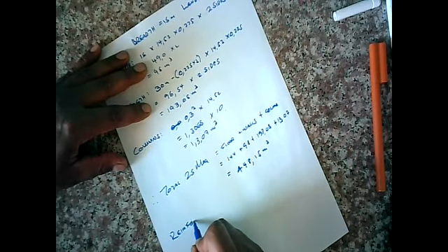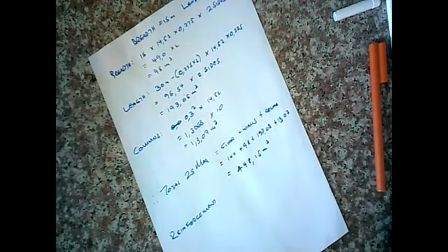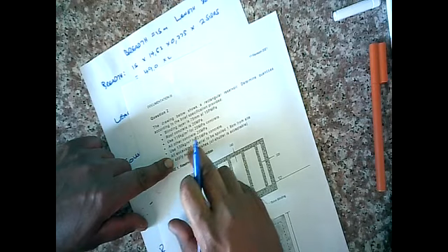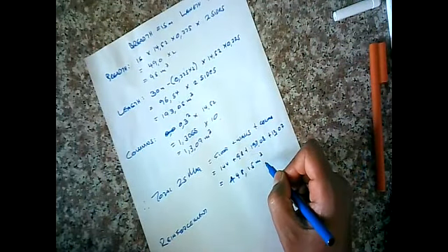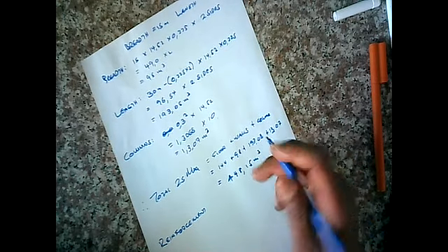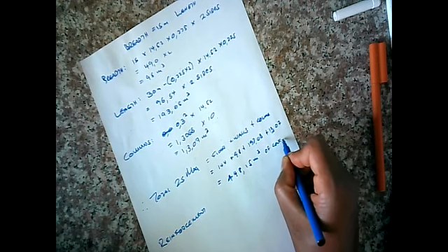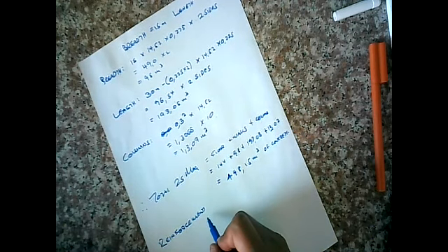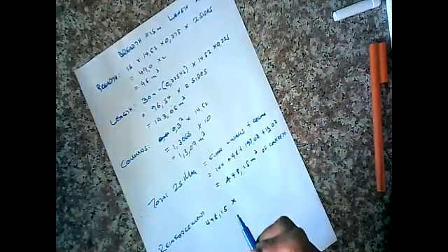Reinforcement. How do we accommodate for the reinforcement condition of the question? And it says for the 25 MPa, we're using 130 kgs per meter cube. Now, if we know the volume, then we know the volume of concrete, and based on that, we know the volume of steel, 48.15 times